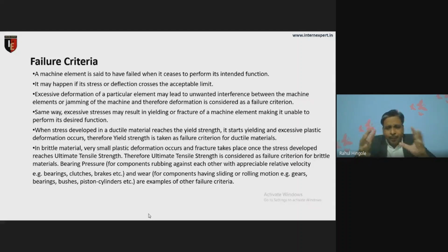In our home, the bearing is there. In a fan, the bearings are placed at the two ends of the shaft. After over 1 year, if noise is coming from your fan, we may say there is a failure of the bearing, not the shaft. Due to the continuous rotation of the bearing, the liquid in it will become less. That liquid is called lubrication. When lubrication becomes less, there is tearing or pitting failure of that bearing. That is also a failure.